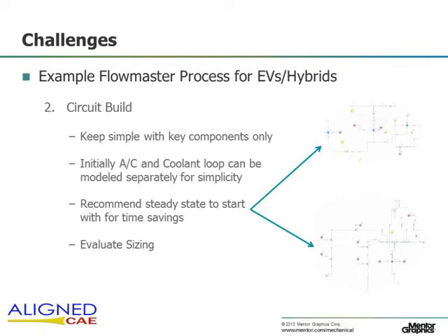What we're trying to do here is to really just evaluate sizing for our components. We want to initially make sure that at an absolute worst case situation, we have available capacity to cool the various parts of the vehicle and also heat various parts of the vehicle. So for the sake of time, we want to keep things very simple here. We run in steady state. So this is just a single point in time. We might run 3 or 4 different points depending on the client's criteria, and come up with a good idea about pump sizing, heat exchanger sizing, and fan sizing at this point.